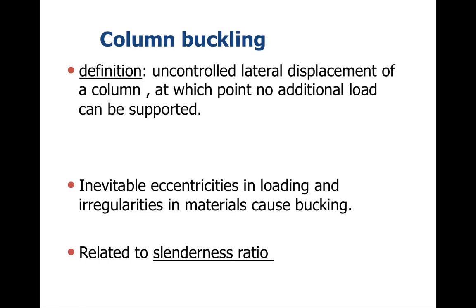And we have to remember that even if we think everything is loaded symmetrically, loaded at the center, there are certainly going to be eccentricities in terms of how the load is really going to be placed, and also certain irregularities of the materials, which are going to cause the buckling. And much of this is related to the slenderness ratio. Slenderness ratio basically being the length divided by the narrowest dimension.